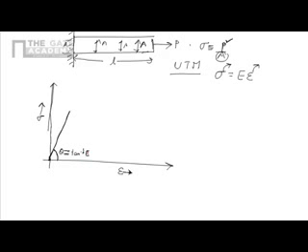Now for some load, the curve increases till a particular point, and after that it droops. What is the meaning of drooping? It flattens out a bit, and for a very small change in force, there's a very large increase in strain, and then it loads up slightly again.